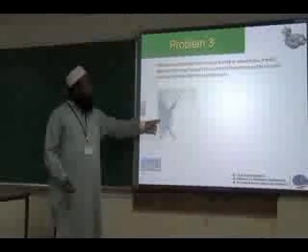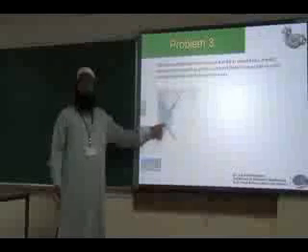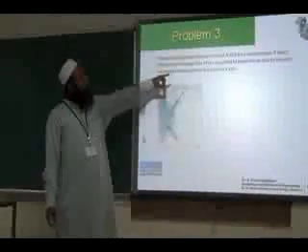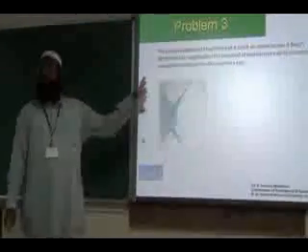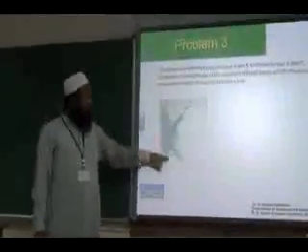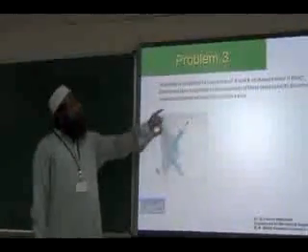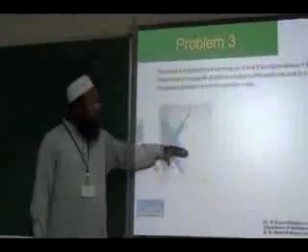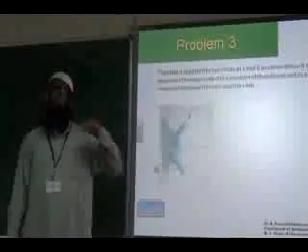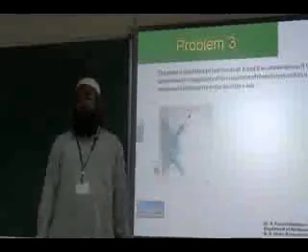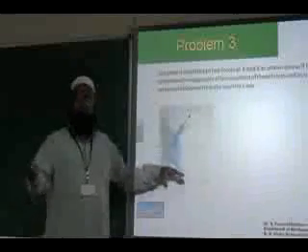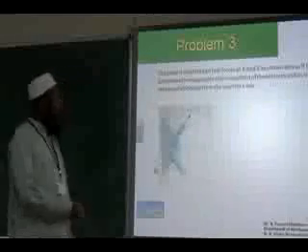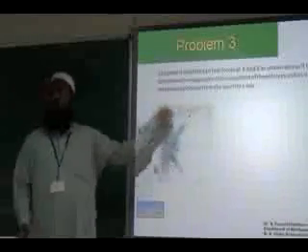Now we are given two forces FA and FB. The angles of both the forces are given as per the problem. If theta is 60, we have to find out the resultant. So this is 60 degrees, this is 40 degrees, and we have to find out the direction and magnitude of the resultant. That means the resultant does not pass through X. We try to solve the problem by assuming it passes through X. No, it's wrong. So now we have to construct the parallelogram and find out the angles.